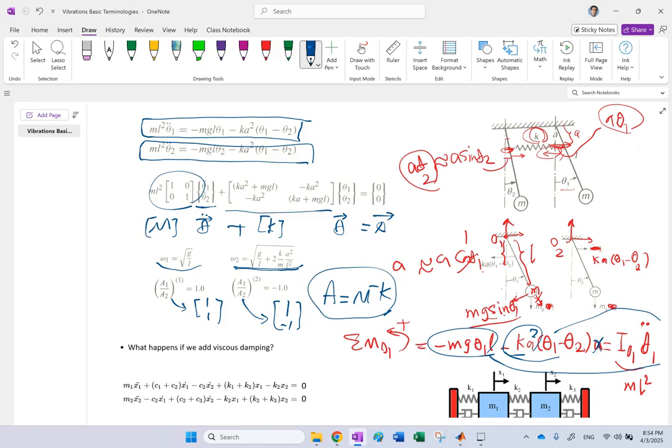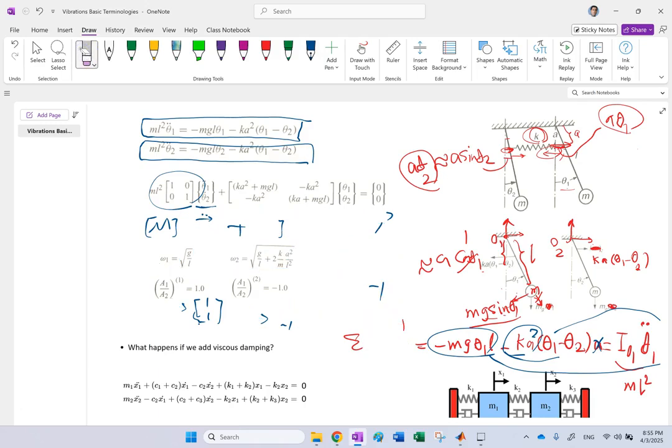Of course, remember again, when you find the eigenvalues of this matrix, lambdas, you have to take a square root of them to get these omegas, and that's where you see these square roots coming from. But the eigenvectors are directly these mode shapes that you can see here. Good. And I leave that part of it, that algebra of it, up to you. What I want to explain here is the meaning of these. So what's the meaning of them? The meaning is this.